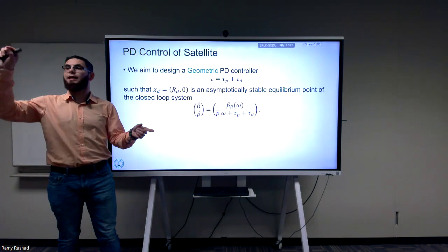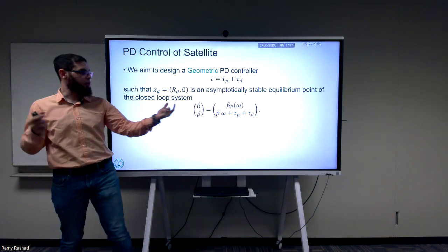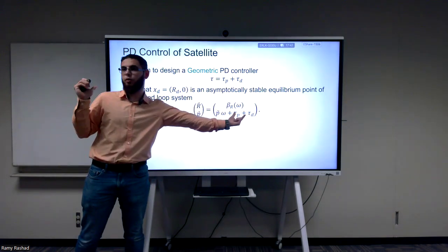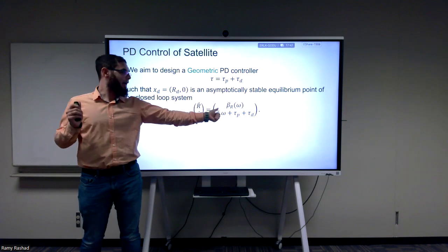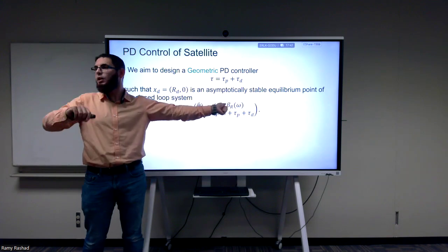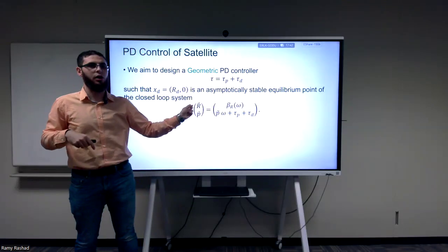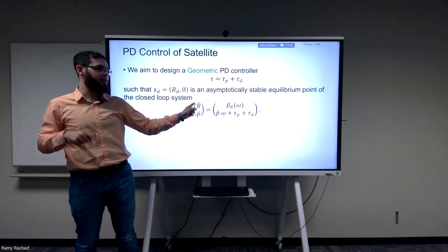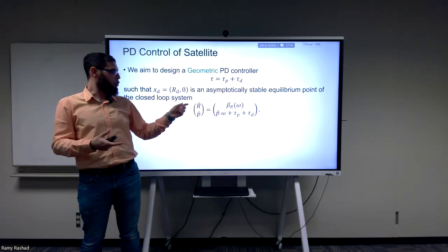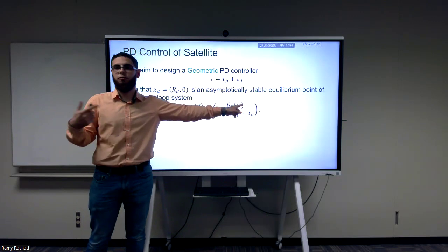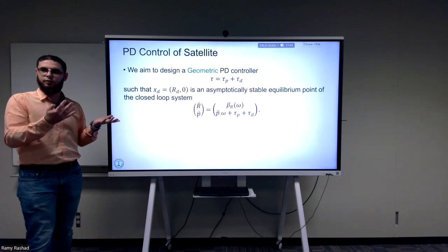So we had the force acting, it was the U. We had the U as a proportional term and U as a derivative term. So both are the same. So these were actually common in both. But this term, we didn't have it, okay? And the one on the top, this nonlinear map that's depending on R, that will map the angular velocity to the R dot, we didn't have that. There we just had that the psi dot is equal to the V. But here, because of the geometry, R dot is not equal to V or omega directly. We just have this map. So this will complicate stuff, like you can imagine.